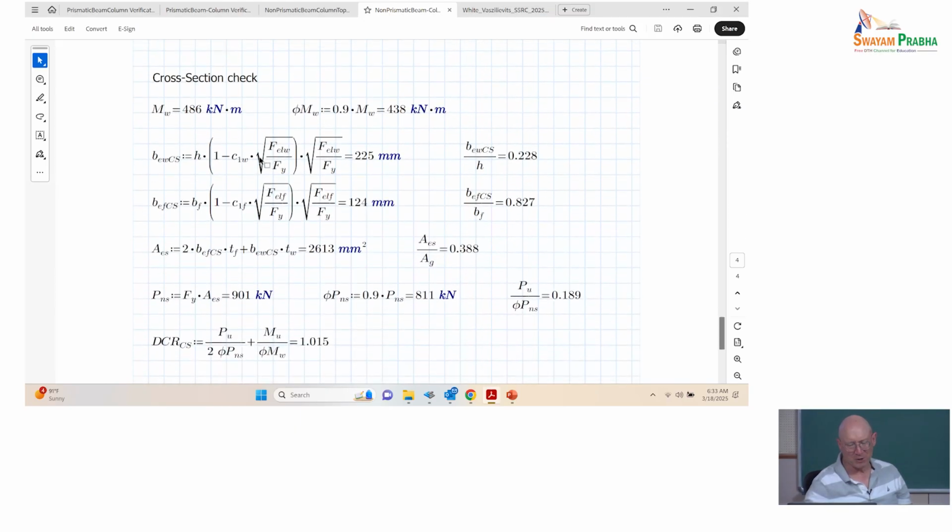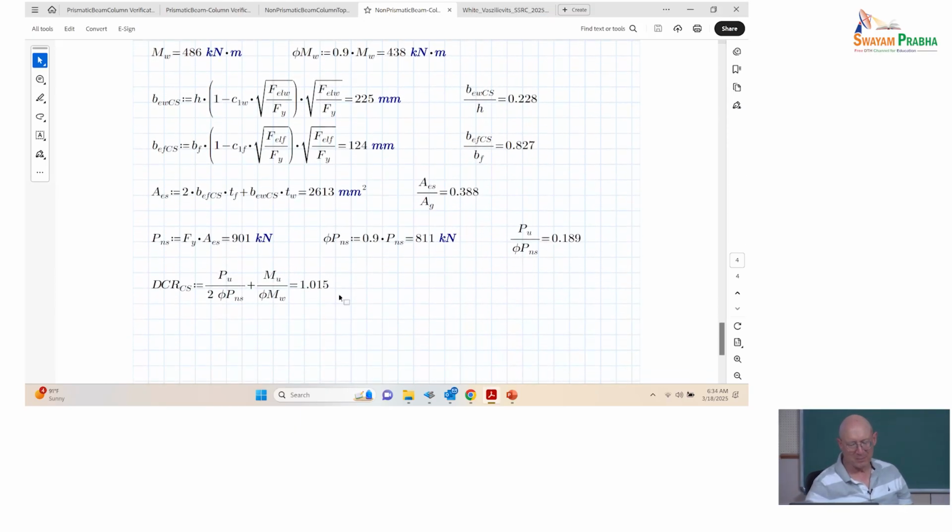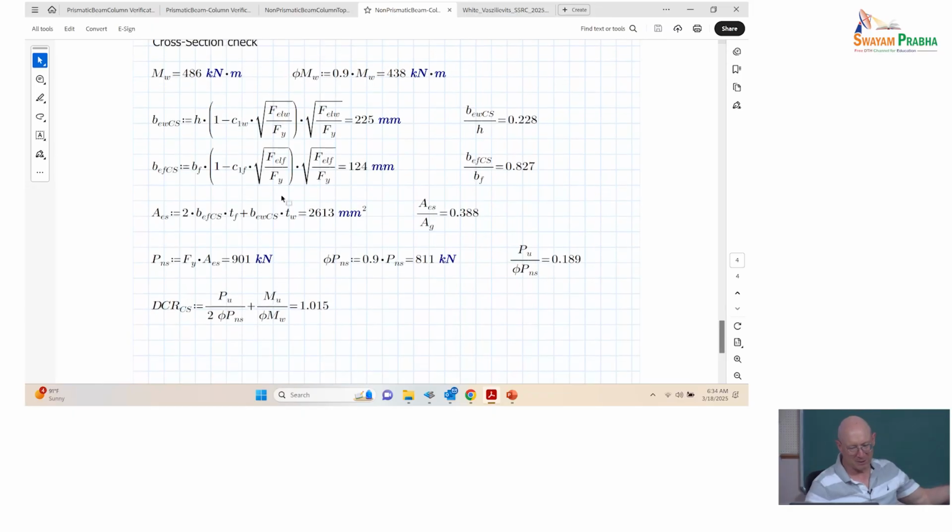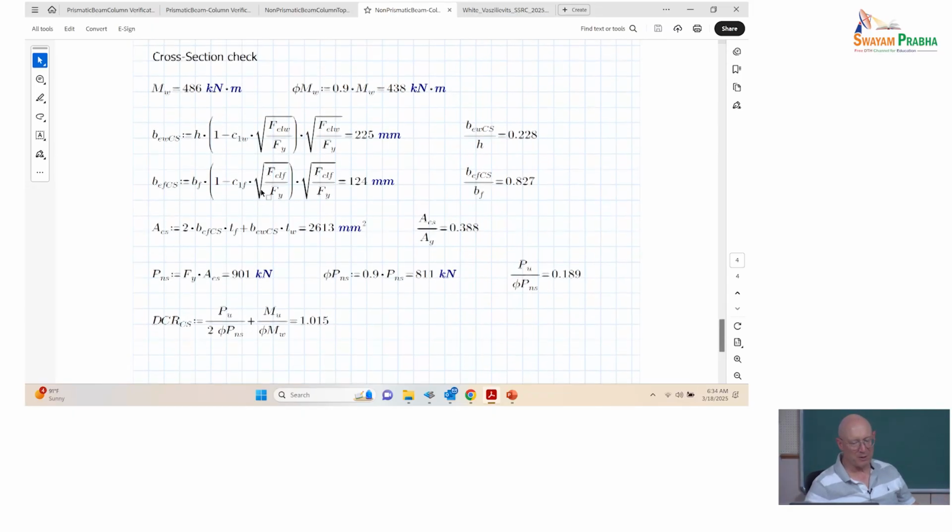And then I'm just showing the cross-section checks at the end here, where in Consteel, the cross-section demand to capacity ratios are used to identify, okay, it's not perfect, but it's generally pretty close. If we go to that cross-section where the cross-section demand to capacity ratio is greatest, we then treat that one cross-section to evaluate the member strength for the member we're considering.